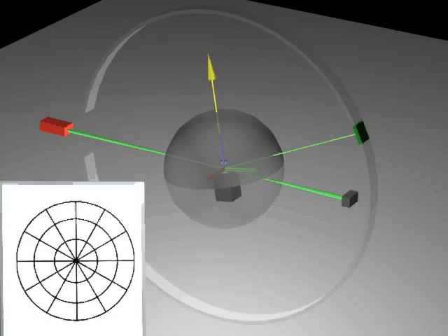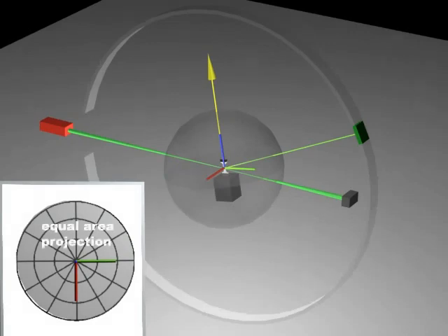Since normal diffraction cannot distinguish between positive and negative plane normals, data can only be associated with an unsigned plane normal or pole. Therefore, all pole figures are centrosymmetric, and we can restrict our attention to just one hemisphere. A two-dimensional projection, equal area in this case, of the hemisphere with the loading direction at its center is shown at the lower left. A red dot indicates that a measurement has been made and recorded at the corresponding location